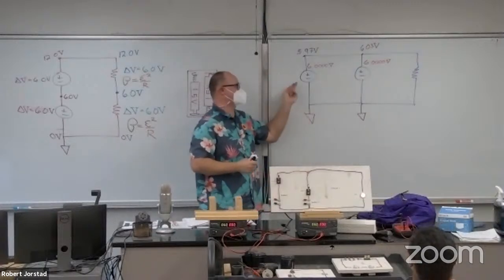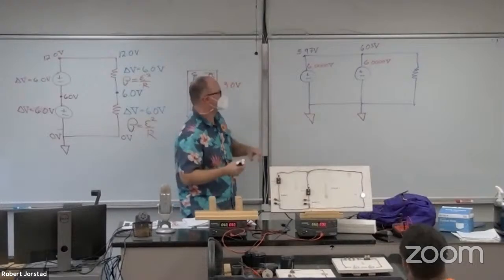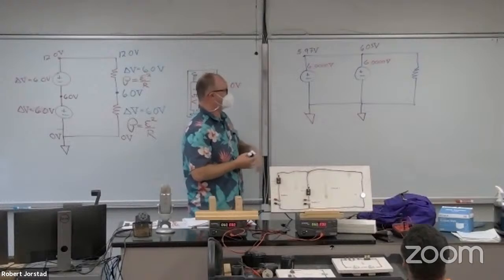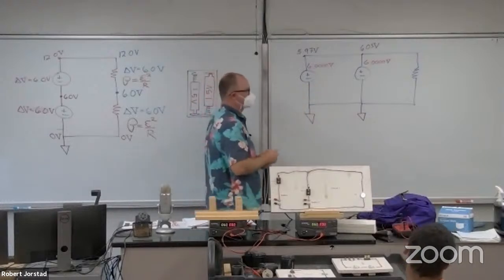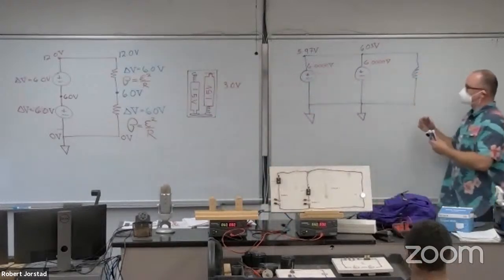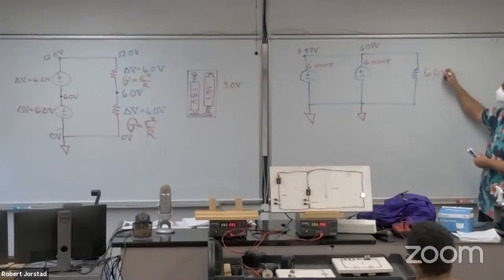If I had exactly the same voltage, they'd be exactly the same. So in practice, our issue is we're going to have dissimilar amounts of current, and one battery is going to try and charge the other one, which we don't want to do. But in this case, if this is all at 6 volts, shouldn't this voltage basically be 6 volts?